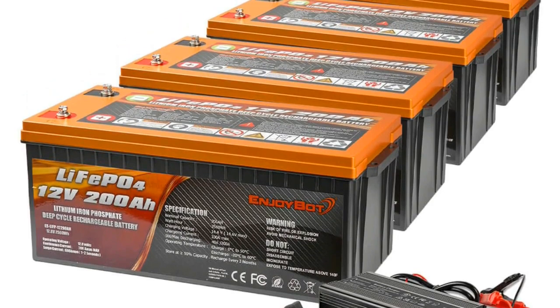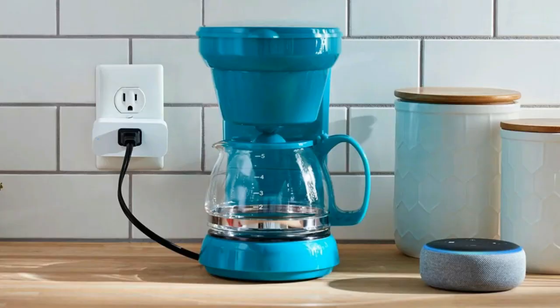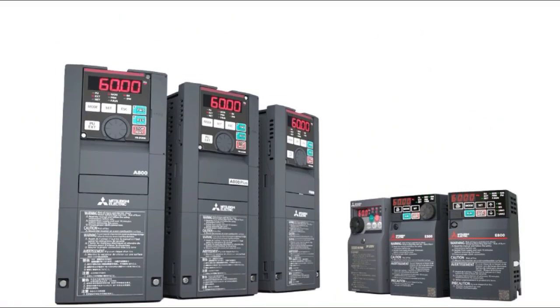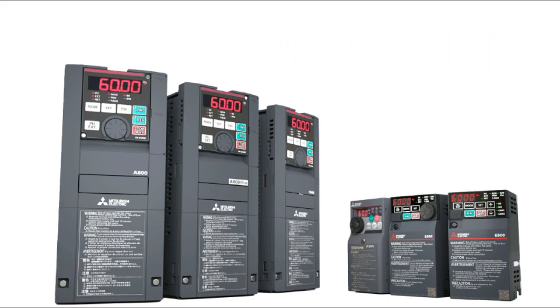If we have a voltage of 12 volts DC and we need 240 volts AC to run a 3000 watt kettle, we first have to do a bit of maths. To power our kettle we want 3000 watts at 240 volts, so to find the current, divide the watts, power, by the voltage and we get 12.5 amps current.